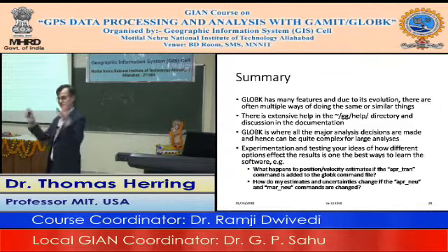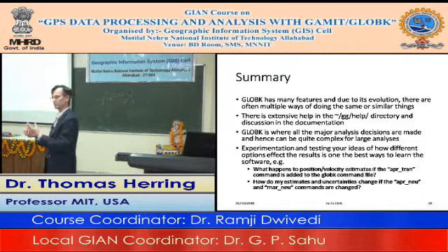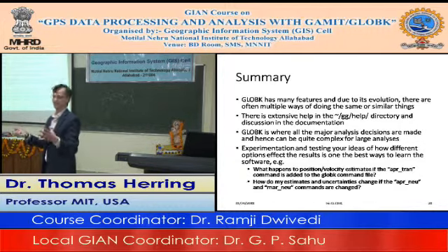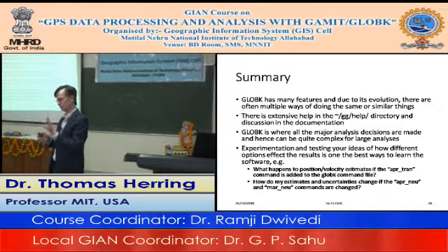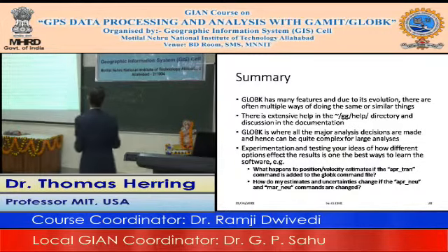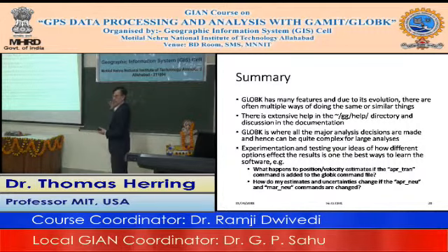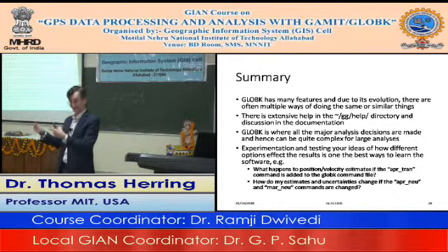A lot of this is you gain experience by thinking about, exactly as you had said, different experiments that I might do. And if you keep them small, you can do them fast. A 15-station network, we know is not going to take very long. And a 30-station network is going to take about 8 times longer, but it's still a short amount of time. And so you can play around and make sure your intuition about what you think should happen does happen. You can also play these games of overlapping more stations and see what the impact is, and then the impact of forcing them apart when you run GLOBK.